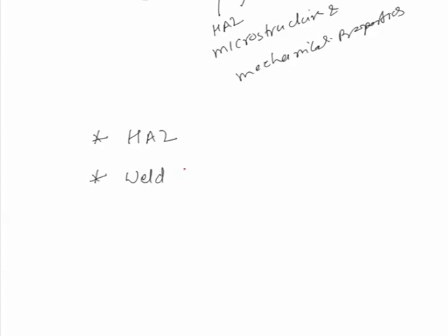So, the weldability will be good, but there are many situations and many metals in which, during or after welding, when the weld metal solidifies, it leads to the development of cracks, pores and inclusions due to the variety of reactions which take place in the weld pool zone, like the formation of inclusions, porosity, evaporation, and loss of alloying elements. So, there are certain things which happen in the weld region due to the application of the heat. Another important thing to consider is what is happening in the weld zone.